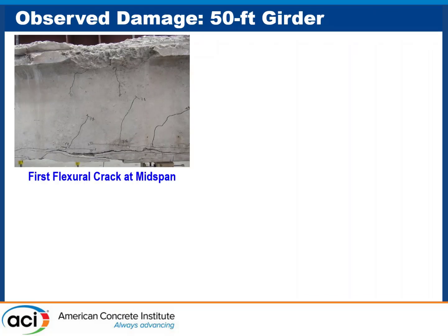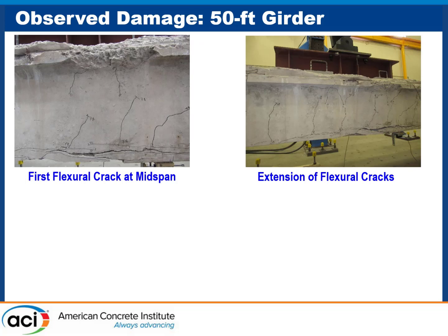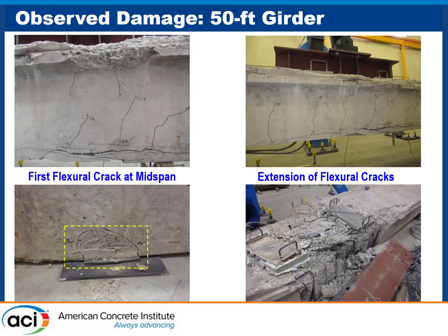Okay, I wanted to show you some of the damages that we saw during the testing. So it was a stepwise testing from low to failure. So typical cracks that you see everywhere. And then at some point, what we saw that the top flange, which had a lot of cover exposure, crushed before you rupture the tendon, so it was a brittle failure, not a ductile one.